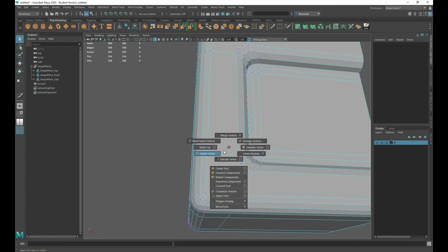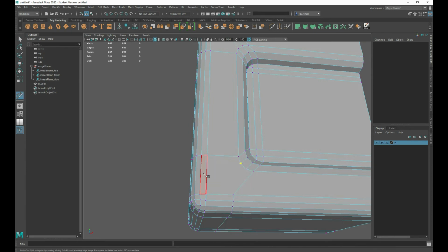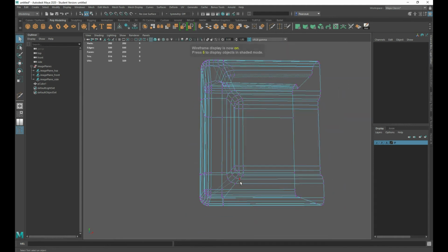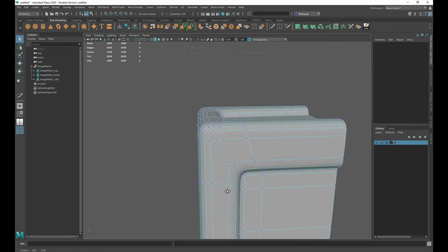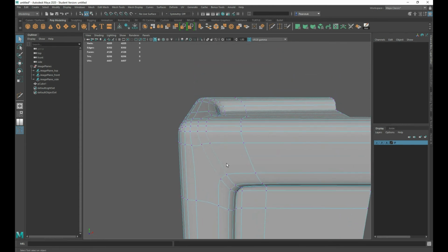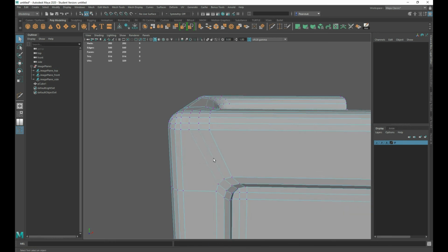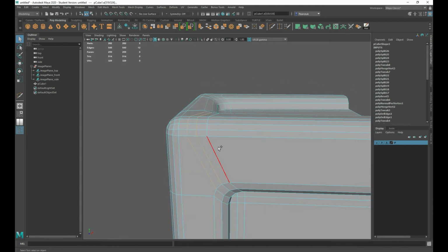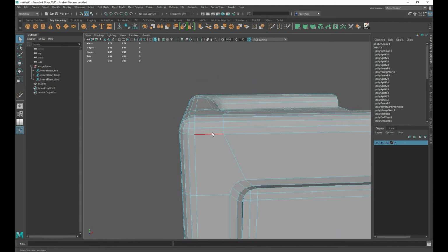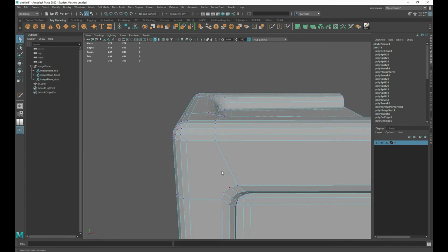Where are we? What am I looking for? Multi-cut tool. And I might tie that off again to the corner. There. Just to support that edge. And we hit smooth. I could have done the same, to be fair, here. And perhaps I will, just for consistency. So select these two edges that I created. Shift right click, delete edge. You want to do shift right click, delete edge, or Control Delete, so make sure you delete the vertices as well. That's another common error that I see.